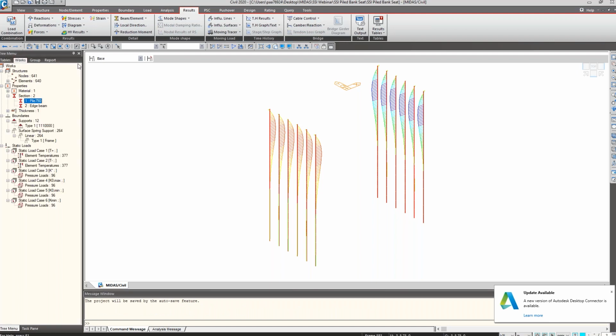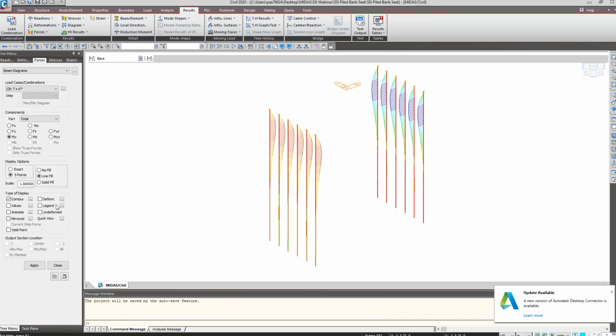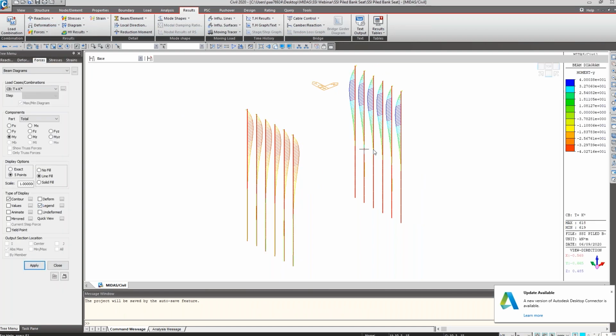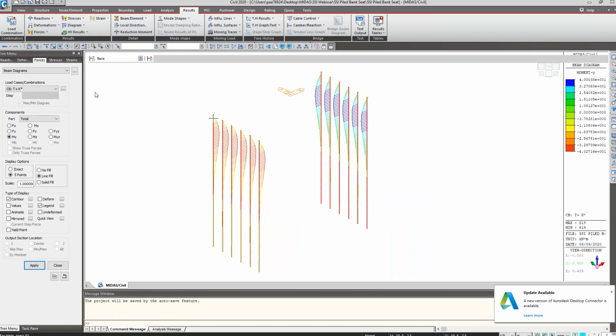Okay, that's good. We're getting these values here. But if we are using K0 min, we are getting much greater values. So for the case of the piles, K-star is not unfavorable. Actually, it's favorable for the expansion case.